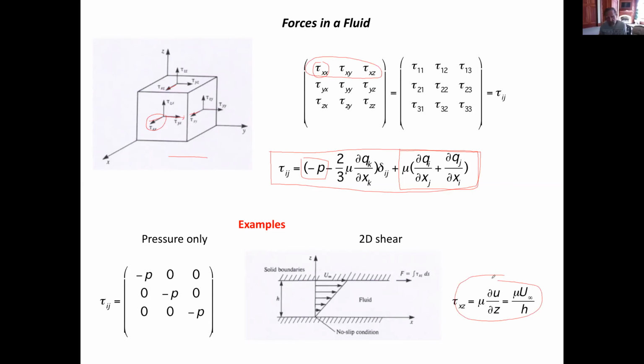To summarize, we're going to see three types of forces in the fluid. One is going to be the body force. We're going to use only gravity, which acts on the mass. So rho g V, which is rho times m, is the force, which is the weight, for example. Could be magnetic forces, could be other forces that act on the volume, the mass, but we're not going to relate to that too much. And then there are the shear forces which exist, so we have to talk about them.